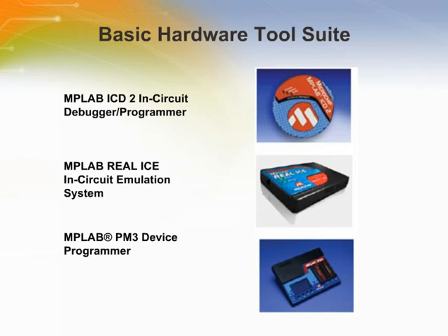As an in-circuit debugger, it will enable the device to single-step or set up to 3 breakpoints and then upload relevant data to the host PC. While the MPLAB ICD2 can program a device, we also support the MPLAB PM3 for low-volume production programming.